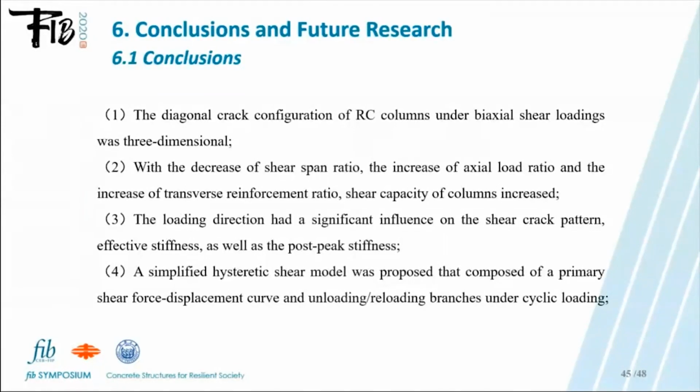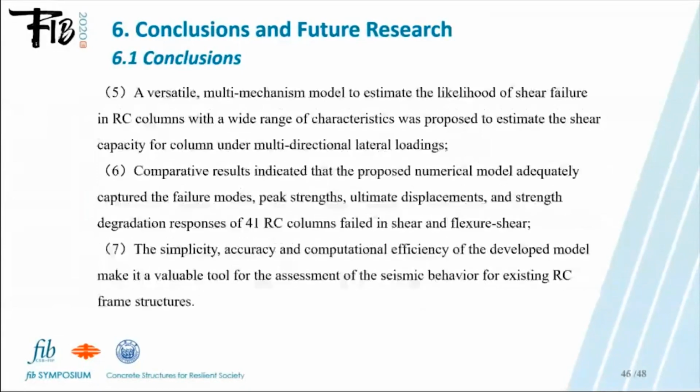The loading direction had a significant influence on the shear crack pattern, effective stiffness, as well as the post-peak stiffness. A simplified hysteretic shear model was proposed in our research project, composed of a primary shear force-displacement curve and unloading and reloading branches under cyclic loading.